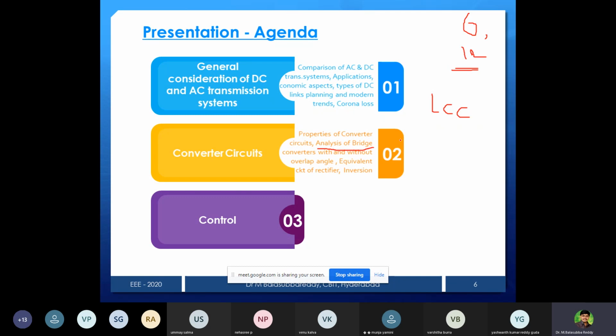In the analysis part, in general in the power electronics case, only one question we notice, the effect of source inductance. But in all the other explanations we will consider the analysis without the source effect. The sequence, I think you may know it, let us consider for a 6 pulse converter. There are devices 1, 3, 5 on the upper side, and on the lower side we also have 3 devices, 4, 6, 2. These are the devices.